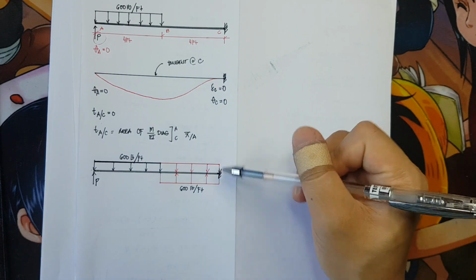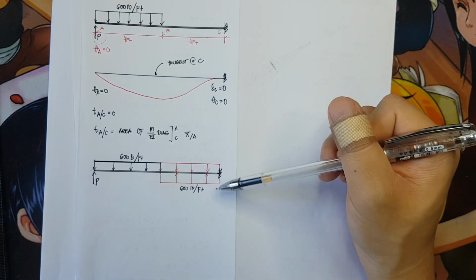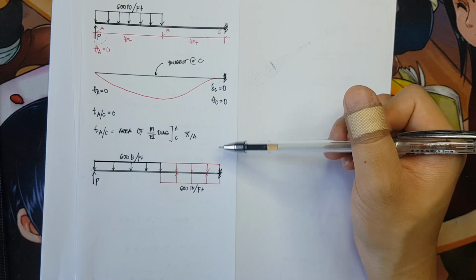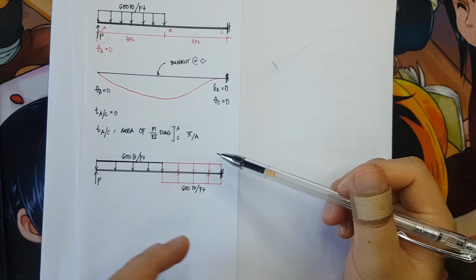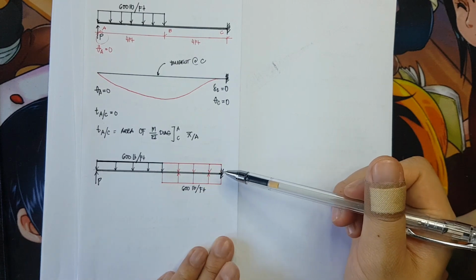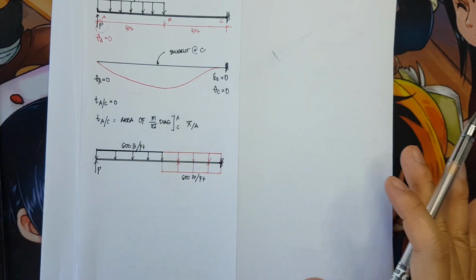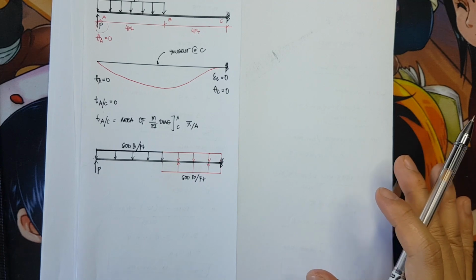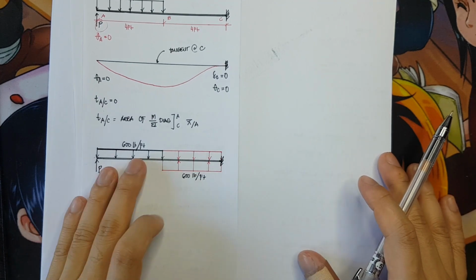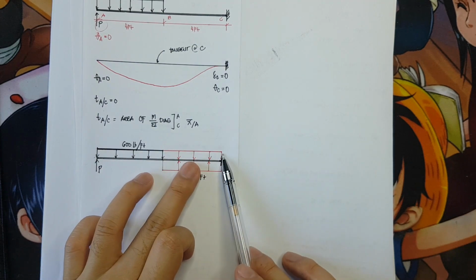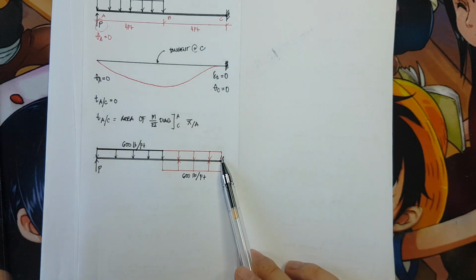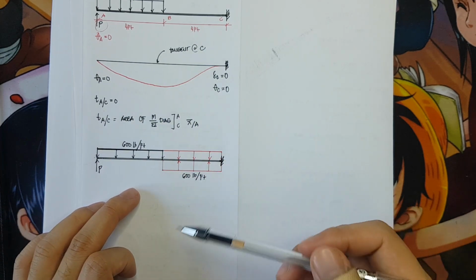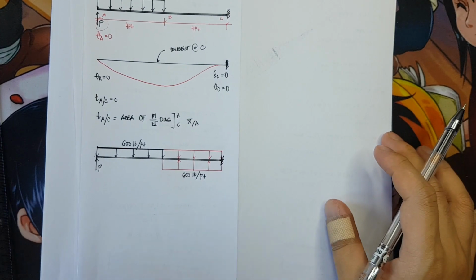According to the procedure, kailangan yung mga reaction, we need to convert that into an applied load. So here we do not need to do that because we will be using the left support for our conversion of cantilever beam. But in the first place, it is a cantilever beam, so we don't need to solve for any reaction then convert it to any applied load. Okay, so like what I've said, I added a continuous load here of 600 pound per feet, and I will cancel that out by introducing a uniformly distributed load at the bottom but with opposite direction.